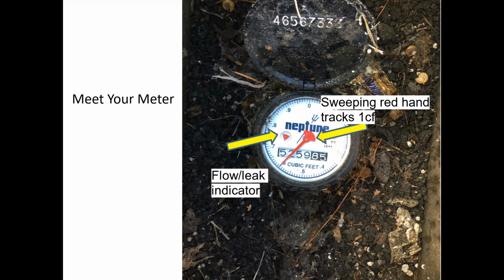For auditing purposes, there's only a couple components that you really need to know about. First is the location of your meter. It's going to be located typically directly out front of your house in the sidewalk. And if you use a wrench or a screwdriver to pop off the lid, this is what it's going to look like inside. You'll have a meter, and the first component that I want you to be familiar with is the red flow leak indicator. It's in the shape of a triangle, and it can detect the smallest amounts of water.